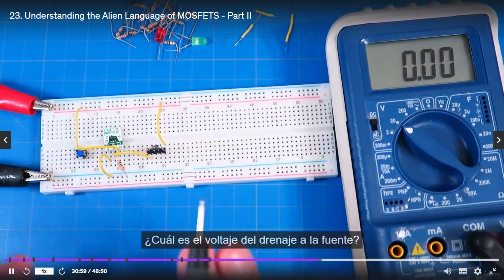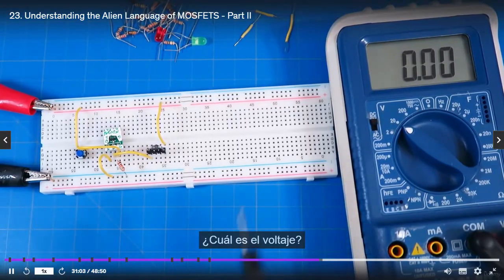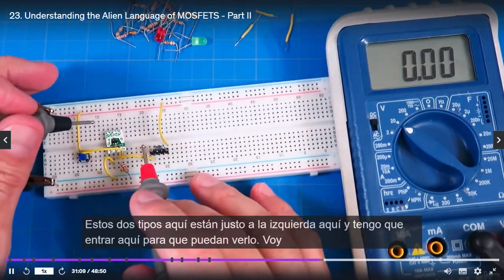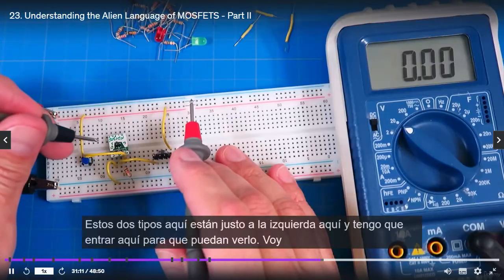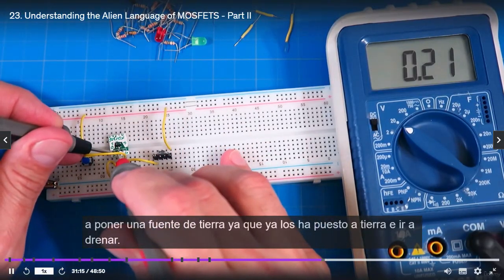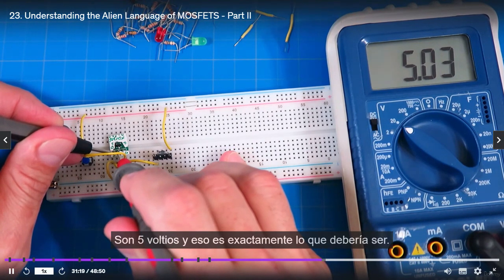What's the voltage from the drain to the source? You got your answer? Let's take a look. Drain to source, these two guys right here on the left. I'm going to put a ground at source since it's already at ground, and go to drain. It's 5 volts, and that's exactly what it should be.